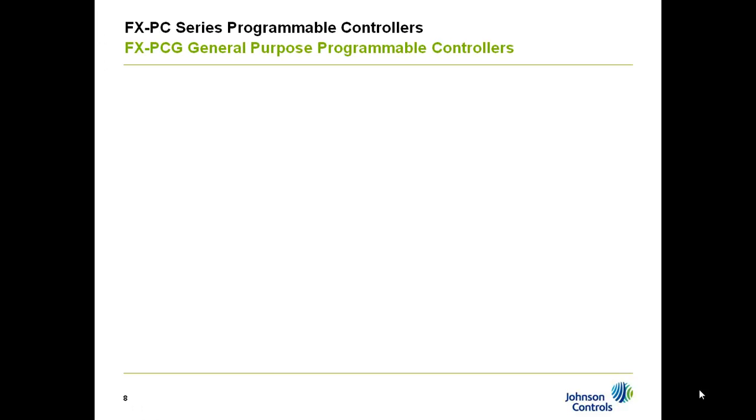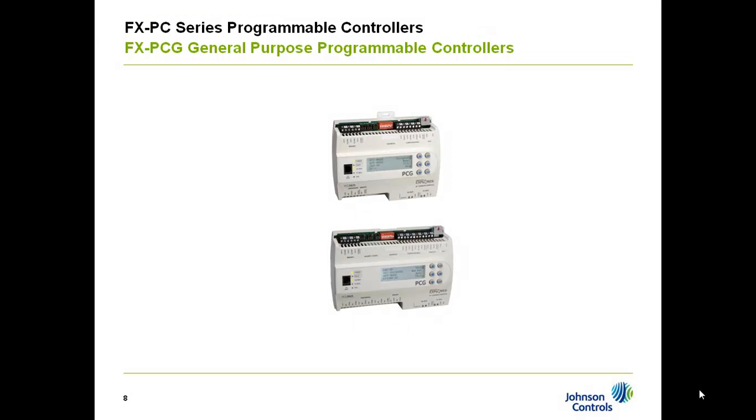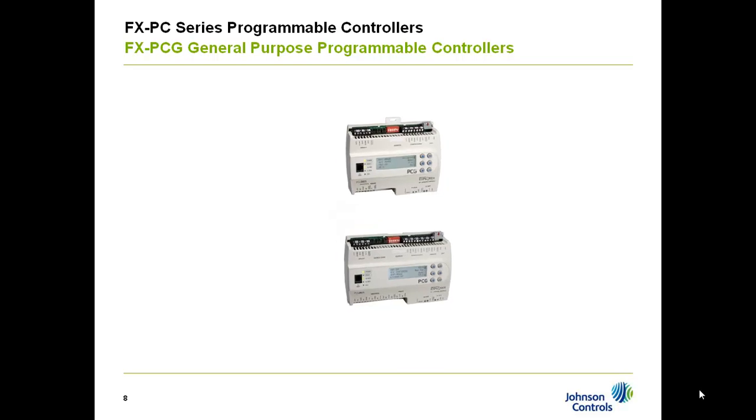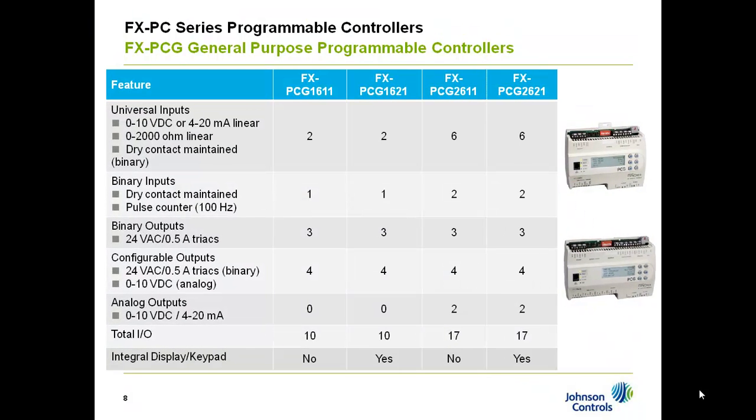The FX-PCG general purpose programmable controller is more suited for a wider range of equipment control applications. We offer 4 models of FX-PCG. The FX-PCG 16 models have 10 total inputs and outputs, and the PCG 26 models have 17 total inputs and outputs. Each model series features an optional integral display and keypad for service techs to gain local access to the controller.